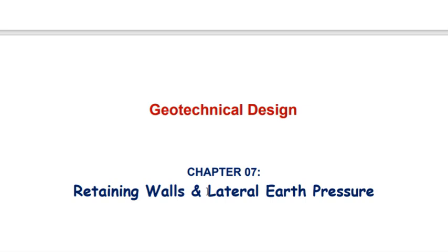more expensive. So usually your first thinking is to design a slope. If you don't have a space, design a retaining wall. Similar to what we said with the case of deep foundation and shallow foundation. You always start with shallow foundation. You never start thinking of deep foundations.